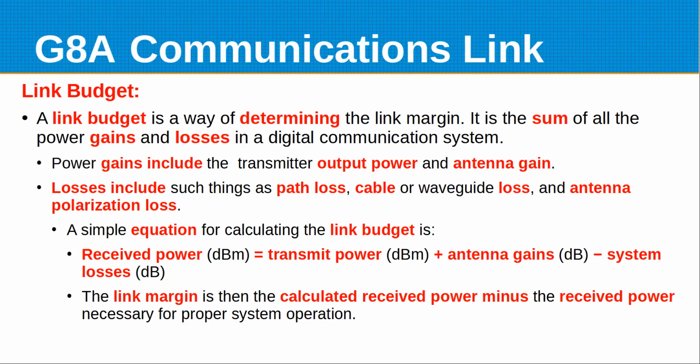But then the big loss is the path loss, which you have to figure from point A to point B, in this case, back. The path loss to the moon and back is 251 dB. So you've got to have a receiver that has a sensitivity of over 100 dB in order to even hear it. That's why most of these things are done with digital modes where you can get a signal to noise ratio that's negative.